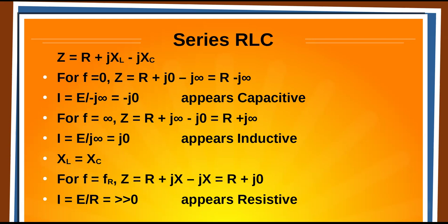At the resonant point, they cancel out, and you get whatever the series resistance is, whether it's a resistor in series or the series resistance of the inductor and capacitor. Does it matter which way the components are arranged in the series circuit, LC or CL? No. Put R in the middle, that doesn't matter, because the current through them is the same, regardless of their position.